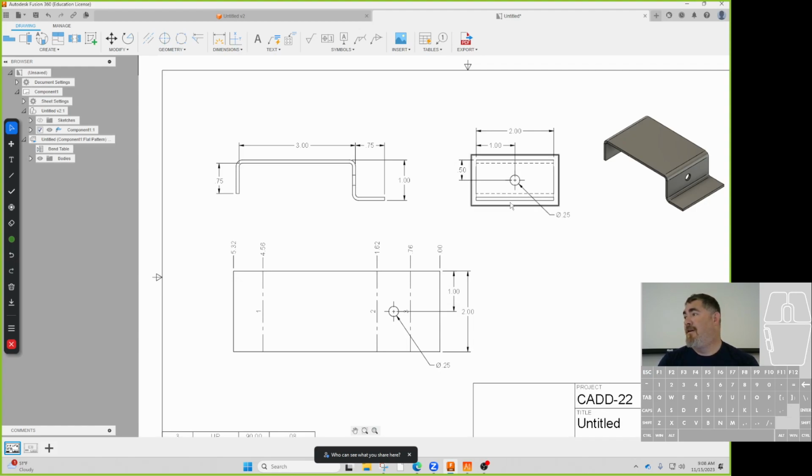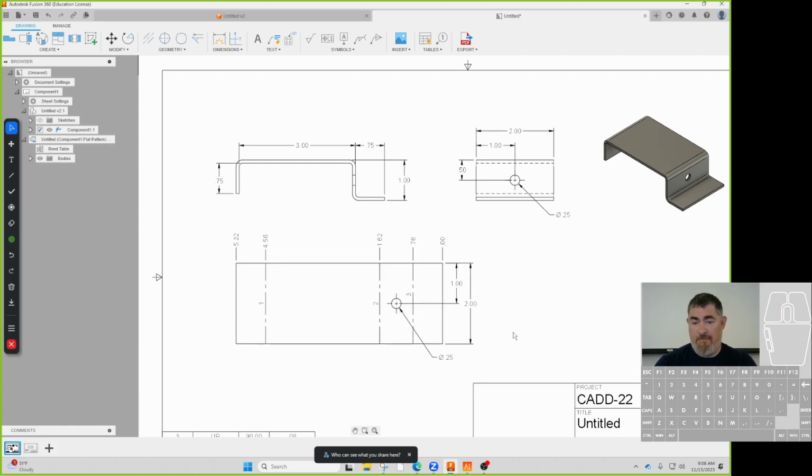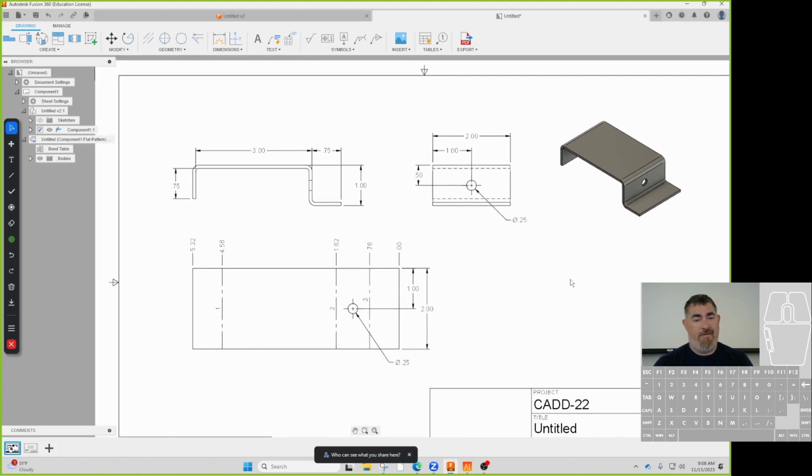No, that's fair. Because even using the same bend radius but using a different bottom die will sometimes change how it bends. So I'd rather give them the freedom to do stuff. Let's move that 3 over there so it's not under the line, to make it look neat. Okay, so this is kind of how I would do this one.